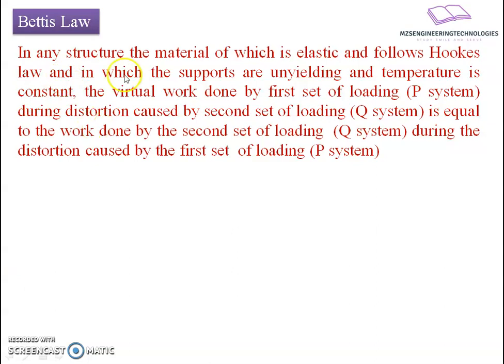What he says is, the material is elastic, meaning it has deformation capabilities, but it follows Hooke's law, meaning within the elastic limit. The supports do not have any yielding, meaning they are not going to sink or settle down, and the temperature effects are also neglected. Temperature is not going to create any extreme stresses in the member.